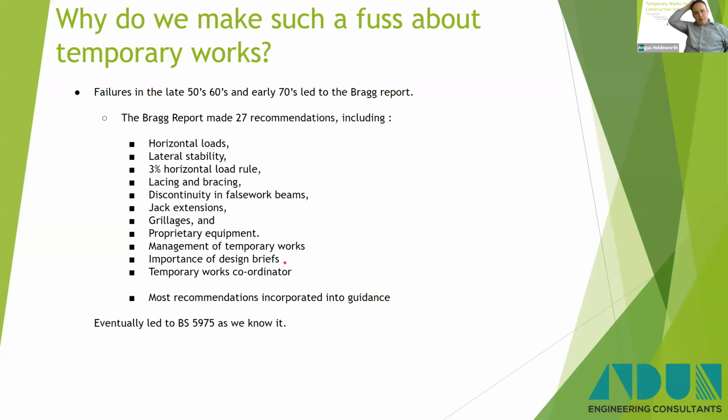Having a good brief that's detailed enough and gives you the information you need can make a big difference to how efficiently temporary works designs are produced. It also introduced the idea of a temporary works coordinator. Now, the temporary works coordinator is the on-site eyes and ears who's making sure that the temporary works design has been managed properly, and that the temporary works have been erected properly.